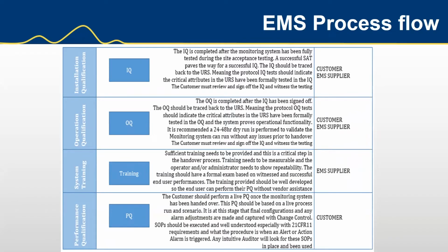The installation qualification is usually completed after the system is fully commissioned. And the IQ, it says installation qualification, okay, but you need to start the IQ with the system fully running. And then you can verify step by step. You go through the IQ protocol and verify each sequence of events is installed as expected, as per manufacturing guidelines, manuals, the URS, and the risk assessment. Same thing with the OQ. The OQ is completed after the IQ has been successfully carried out.